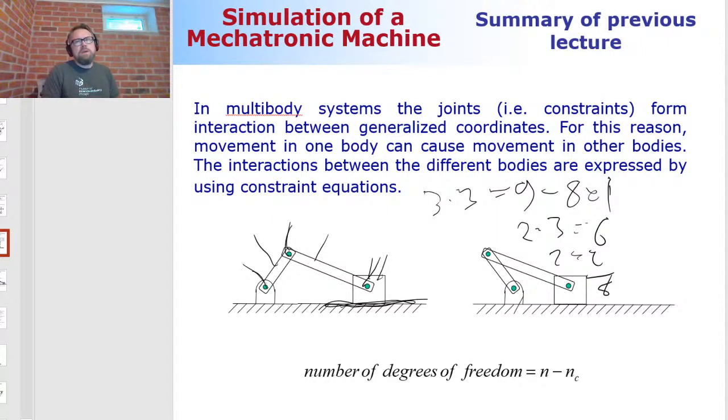And it can move one way only. The piston cannot travel in, say, this direction because it's constrained to ground. So it cannot go in the minus y direction. The connecting rod cannot decide to move here. It cannot do it because it's constrained to these 2 other bodies. So that's what the degrees of freedom means. It's the different ways that the structure can move. Okay.